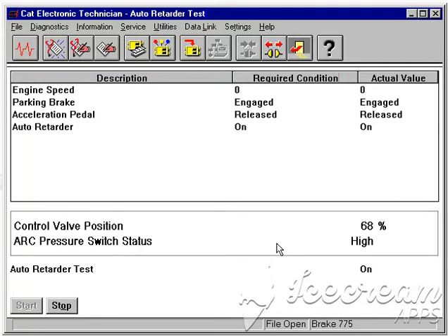You can also check the whole brake system by putting a pressure gauge on the slack adjuster. Air system pressure goes to about 120 psi, and the master cylinder's ratio is about 6.6 to 1, so you should see a pressure of between 700 and 800 psi on the slack adjuster.